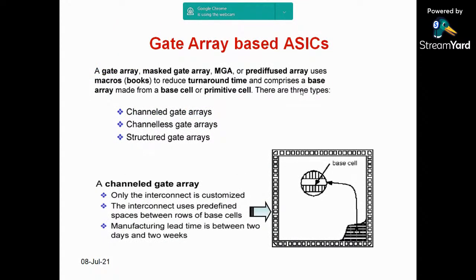Now, I told you, right, half-baked roti or chapati, that is the gate array. A gate array is something not only pre-designed or pre-tested, they are pre-manufactured. Manufactured on the silicon wafer, but the packaging will not be done. Please understand, the packaging will not be done. They will be manufactured and left open.